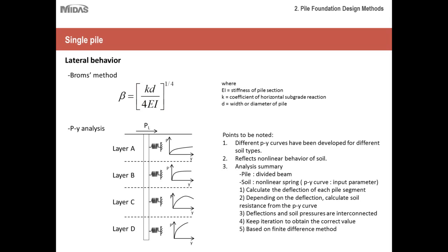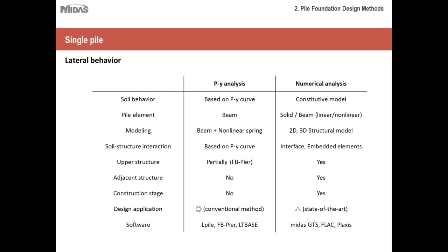Now, since this session is more geared towards numerical analysis, let's see this alternate approach of numerical analysis. How is it compared to PY analysis? So here you can see a quick comparison. Let's start with soil behavior. Under PY analysis, we use PY curves to represent the soil behavior, whereas in numerical analysis, we use constitutive models that are based on realistic data and represent the soil more accurately than approximate PY curves and using springs.